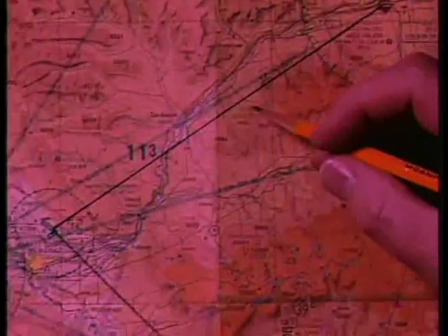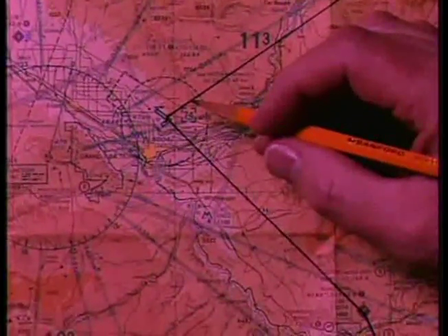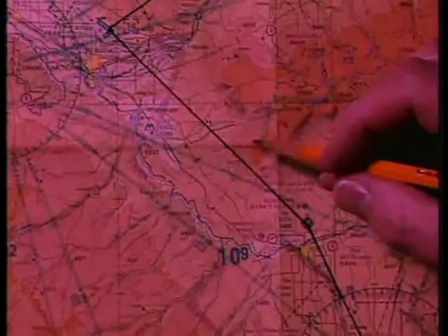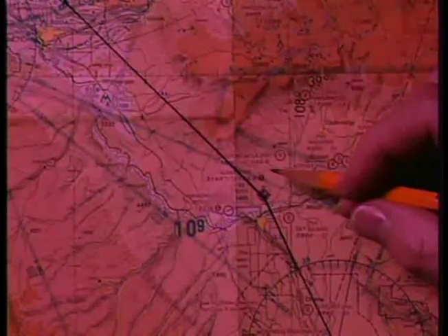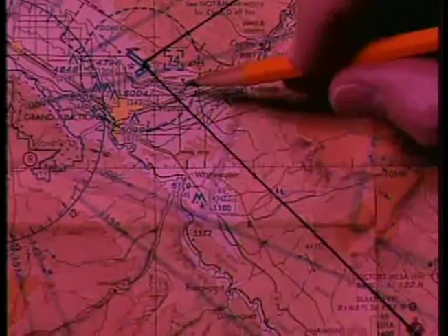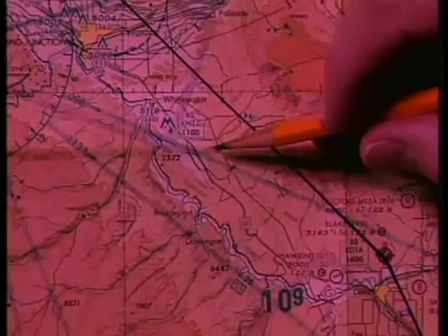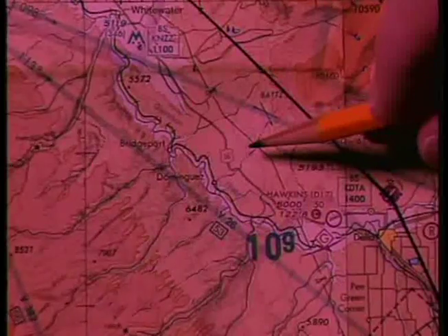Lighted areas typically indicate structures that may obstruct a landing area. Although highways may provide places to land, you need to be aware of the possibility of power lines that are often located along and across them. As a safety precaution, many pilots alter their route at night to keep within a reasonable distance of lighted airports for most of the flight. When planning for an emergency landing at night, one of the primary considerations should include selecting a landing area close to public access if possible.